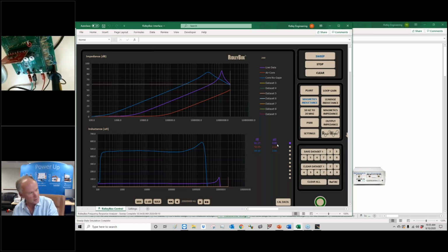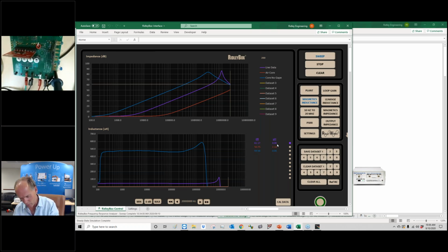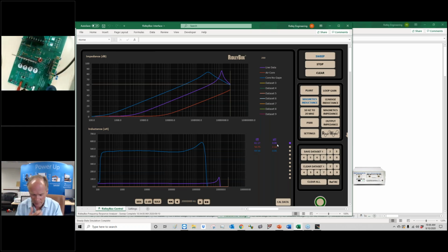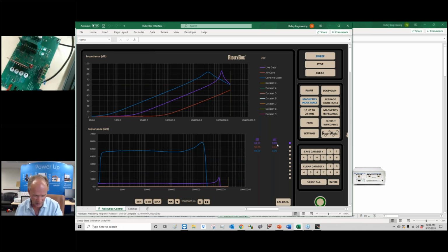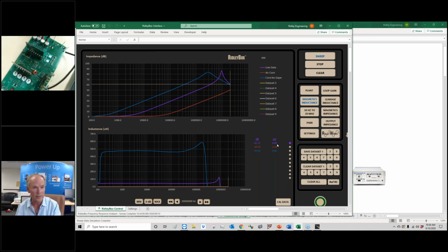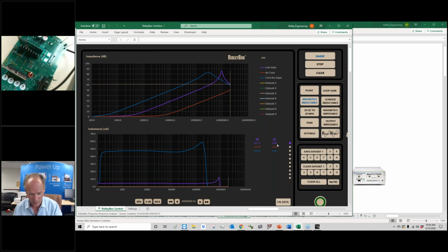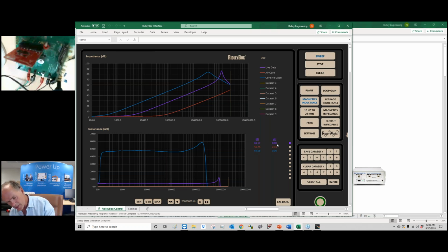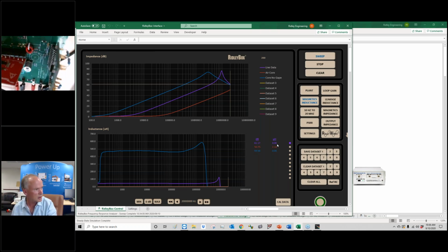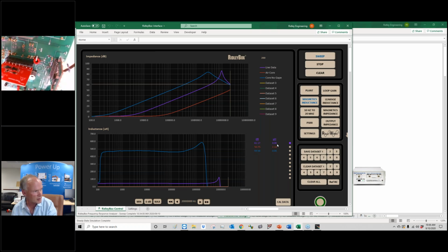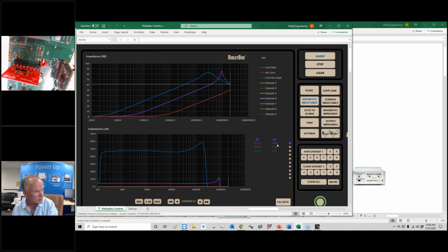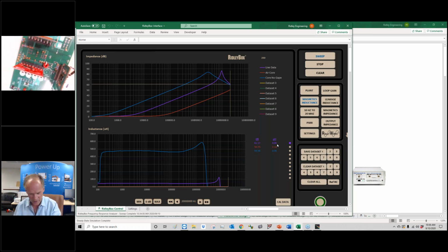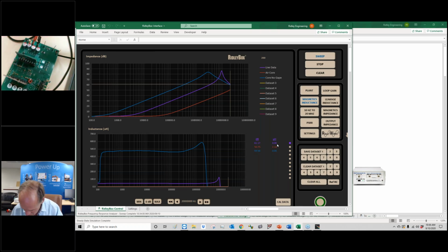And we've laid out the pins here and the sockets to take up to 4 different transformer sizes. So we've done converters on this board anywhere from, you can go as low as you like, but we've gone all the way up to 400 watts. Got a 400 watt flyback on this board and a 400 watt forward converter on this board. Switches on the primary. Let's see that red board there. That's my friends at EPC. They designed a 2-switch forward or 2-switch flyback board for us there. So we've got some nice fast switches in our device.